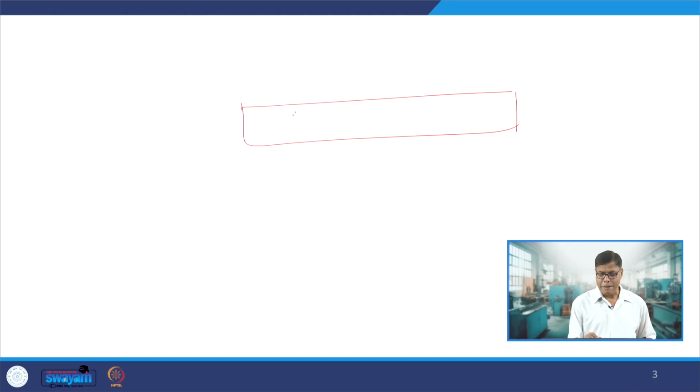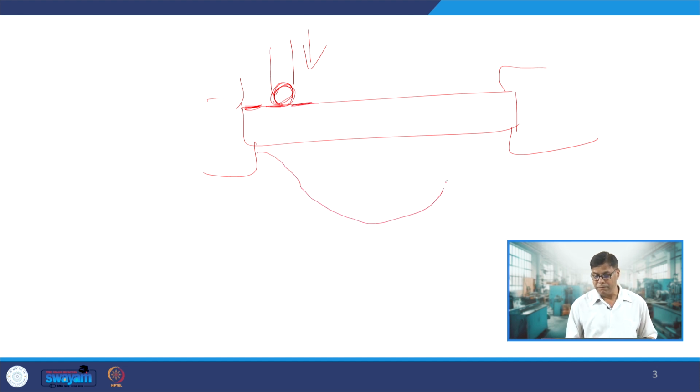Now, this kind of shaping can be done in the closed die or open die. So, this is another approach. In the incremental forming approach, what we do is, say at the ends the sheet is placed like this, and then a round tipped, hemispherical shaped tool is allowed to deform the sheet in a controlled way, stepwise. So, initially it will be working here, then here, then here, and gradually the metal sheet will be deformed as per the shape which is desired. So, this kind of thing will be done in steps.